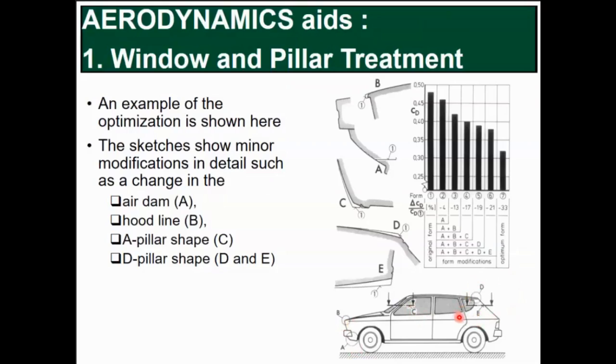So normally the engineers or technologists will do a design and do the optimization of the design to reduce the drag. Okay, for example, they will make the sharp edge to be round. Okay? For example, round, no sharp edge, and then increase some measurement here. For example, at B area, okay, at D area, and then it will cause the drag coefficient to reduce.